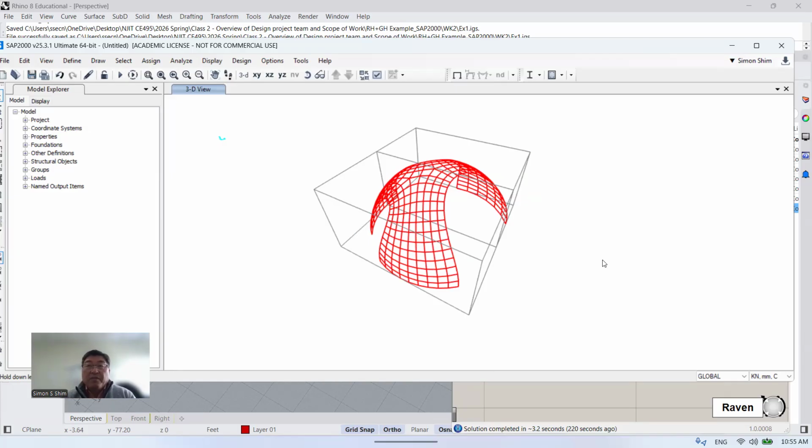We need to define the elevation for the building and set each floor-to-floor height. From a geometry standpoint, we need to add a few things, and we're going to use a slightly different procedure to export the geometry and import it to SAP. But up to here, if you are successful up to SAP, let me know.